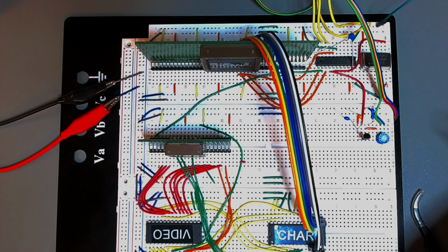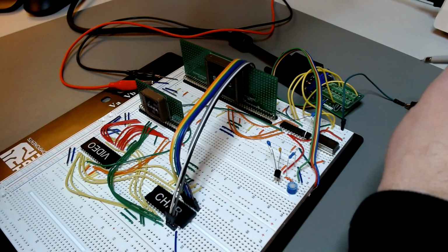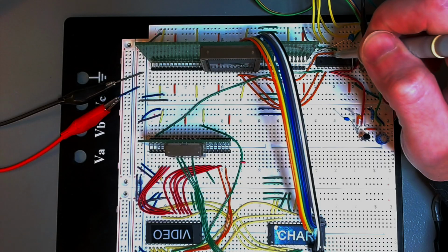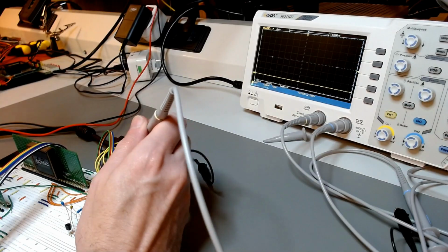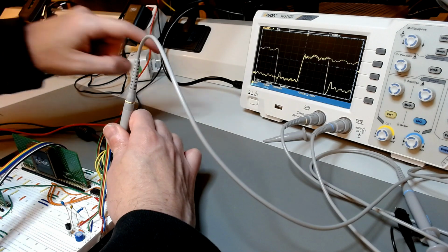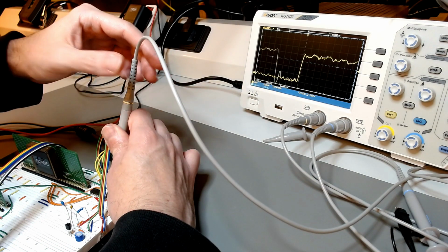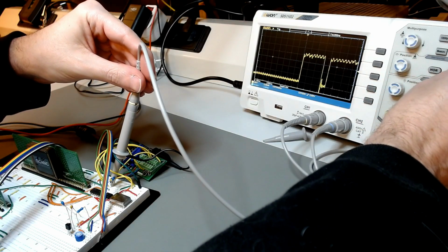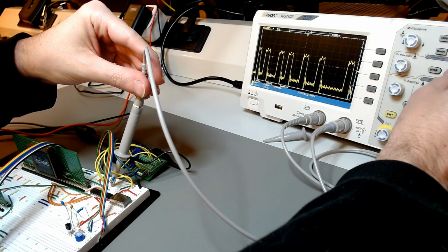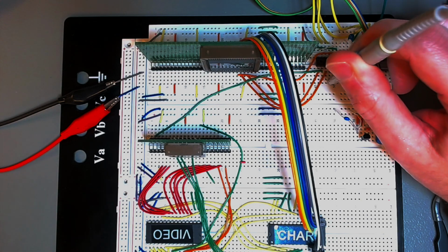Let's have a look at the signals, particularly the green color signal that's produced by SCANC. It comes here into this orange wire here. So if we probe the signal the way it comes out of SCANC, you see it's 1, 2, 3, around 4 volts, quite a bit of rippling. But it is a digital signal if you see it at this scale.